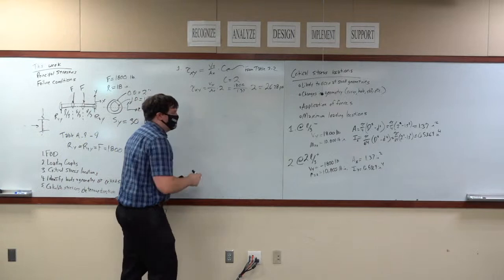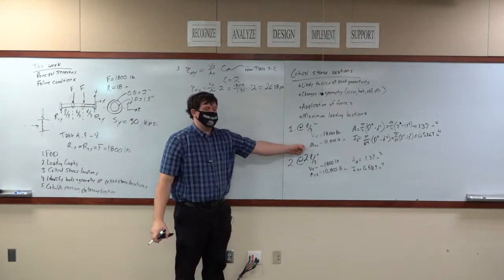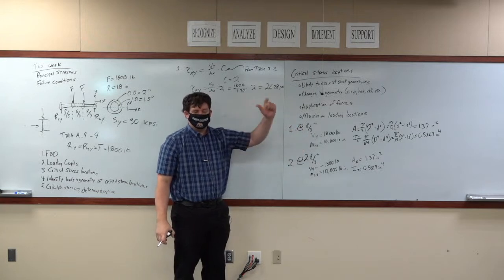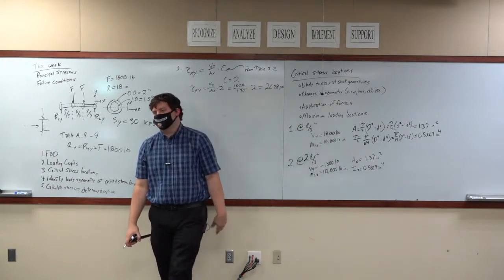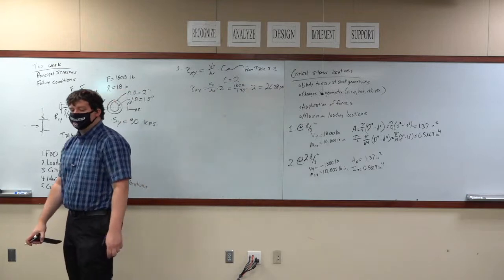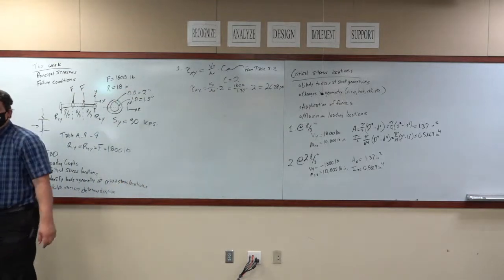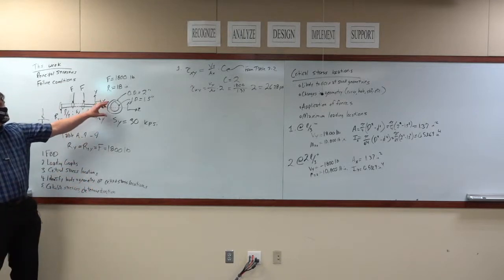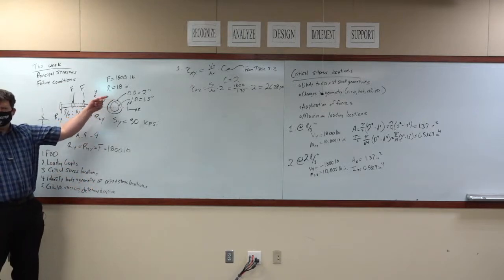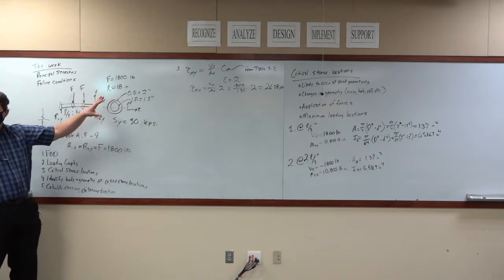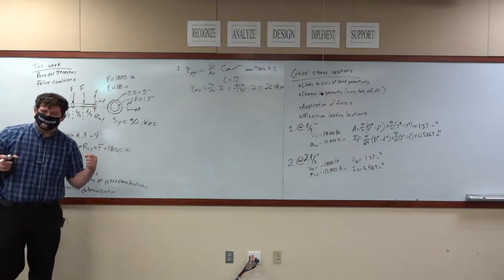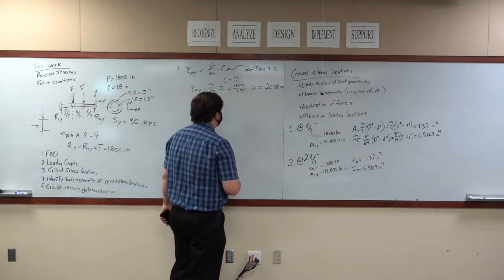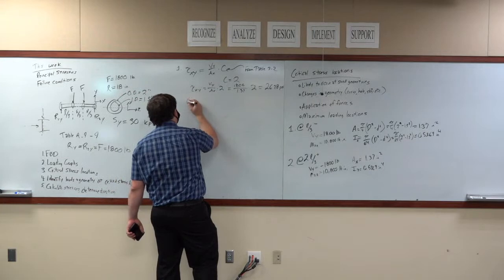All right. What kind of stress is created by a moment load? Is it a shear stress or a normal stress? It is a normal stress. Because what happens is the top is in tension, the bottom is in compression, or the other way around. And a tension or compression is a normal stress. It squishes or stretches it out. Okay? So this is a sigma.